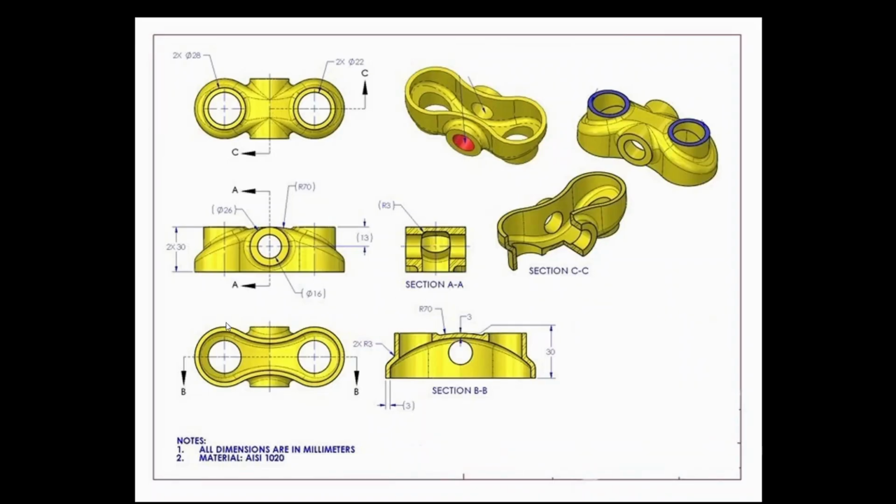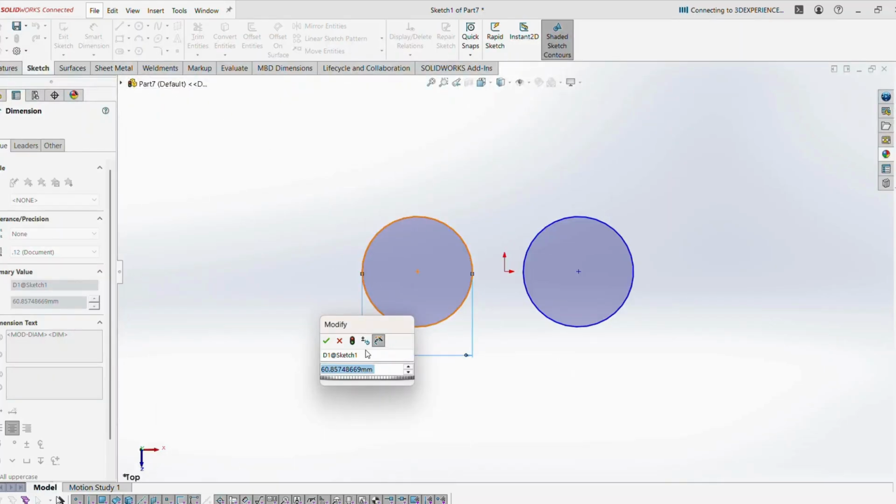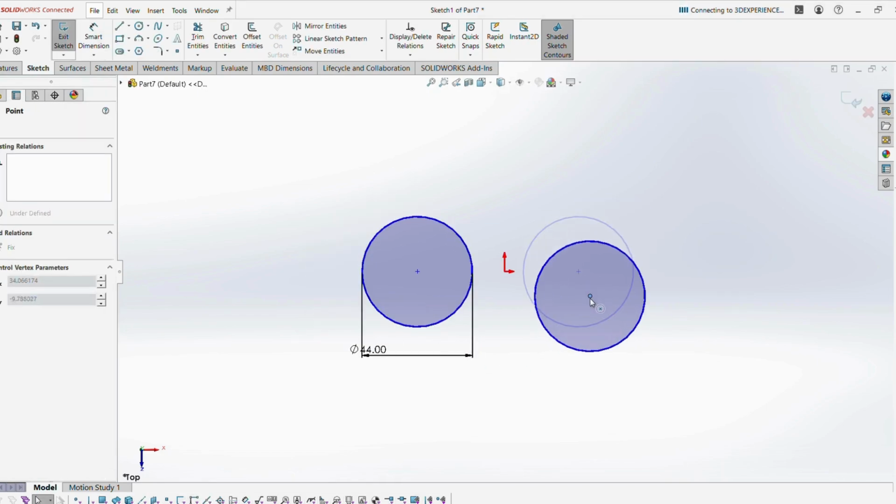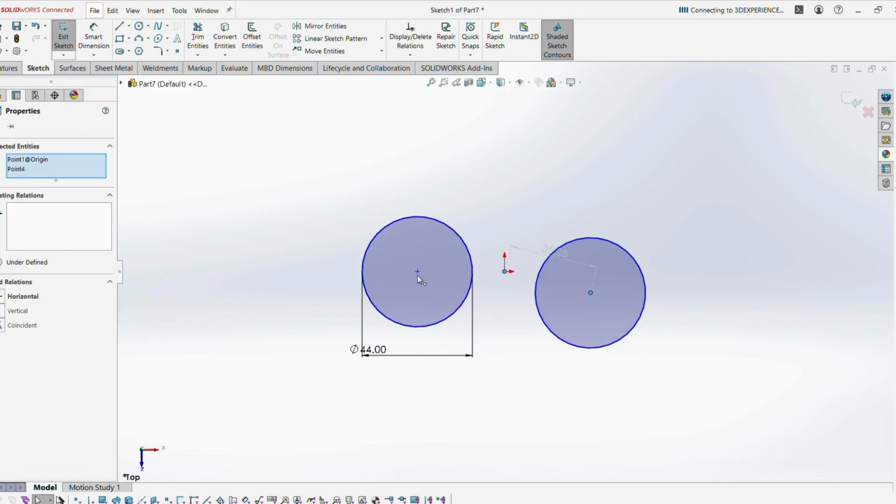What's the value for the diameter of the innermost circle? If you look at the view, the innermost circular profile has the dimension of 22 mm diameter. So the outermost circle must be 22 mm radius. Here we can give the diameter value, so just mention 44 mm.